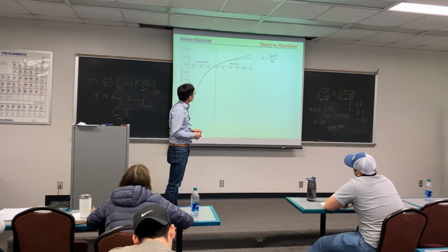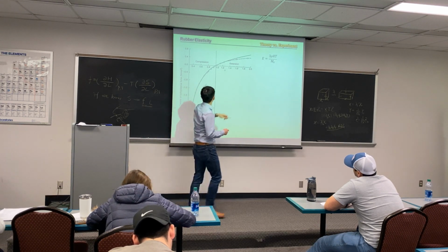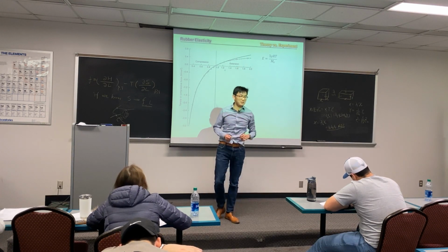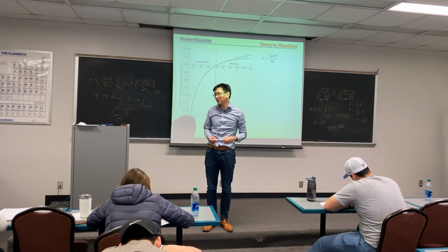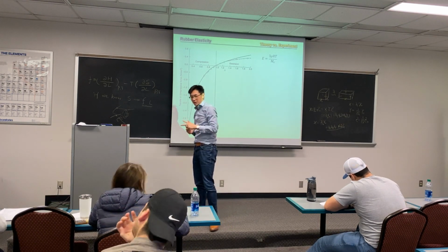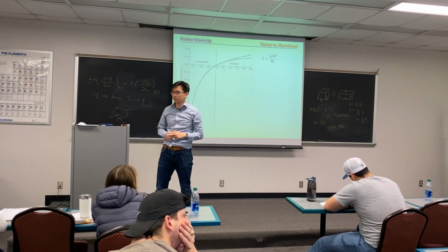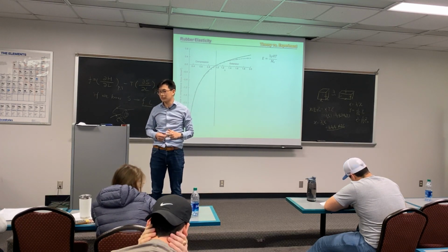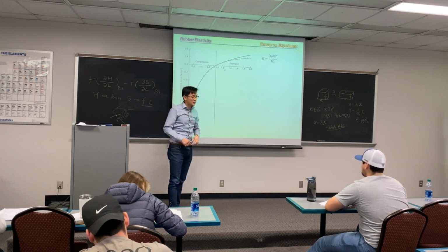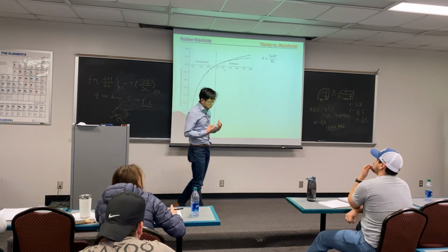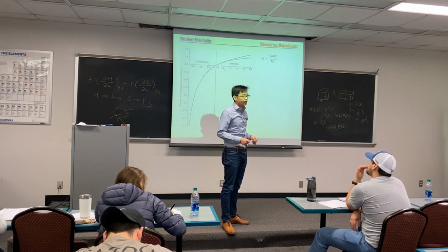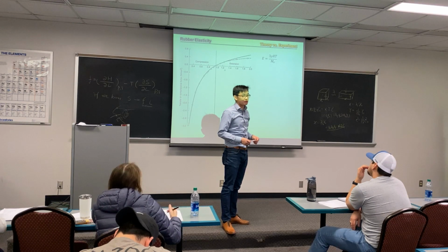We will talk a little bit more about why there is deviation, as you can see, we made quite some assumptions: incompressibility, affine network. We will address this in the last lecture after you come back from Thanksgiving. But the conclusion for today is, despite this being a very simple, easy theory, it works very well for ideal elastomers.